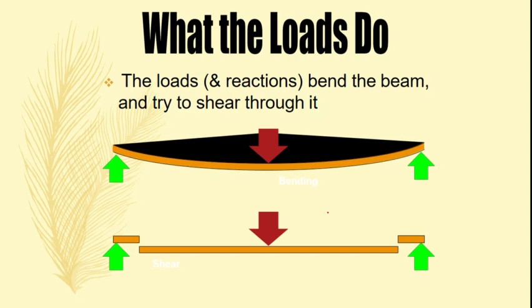This transverse load causes variable shear force and variable bending moments. Hence, we have to know the variation of the shear force and bending moment over the length of the beam, and also calculate their maximum values. That is why we draw the shear force diagram and bending moment diagram, and the maximum values of shear force and bending moment are used in designing the beam under strength criteria.